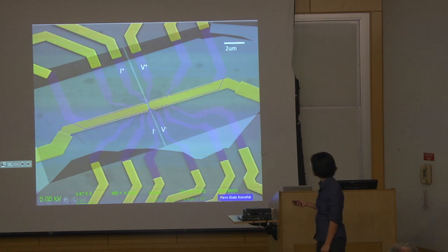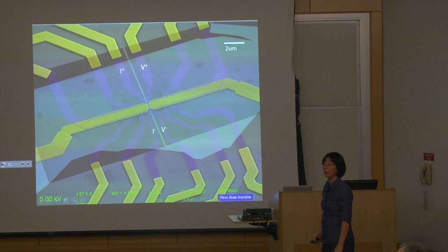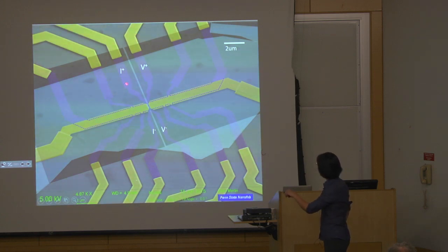The segments outside of the gate region are semi-metal, and these are ungapped bilayer graphene. So this is heavily doped, because they're only sitting on the back gate. The top gate is only here and there, so these are good leads to the graphene. We're using graphene leads to contact the channel, correct.